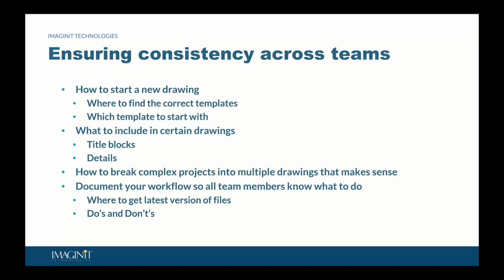One of the other things I have run across a number of times is to be very careful if you are migrating up to ACC. What I typically recommend is, if you're going to go to ACC, start your new projects in there, and only migrate the projects you absolutely have to move to ACC, because of ACC data shortcuts with BIM Collaborate Pro.